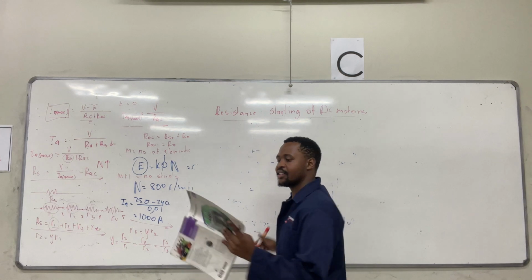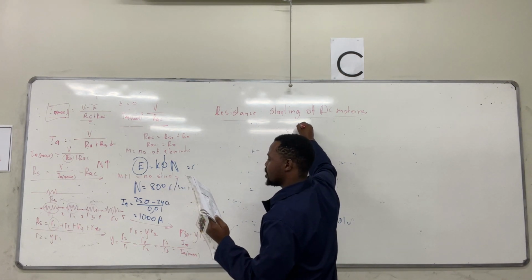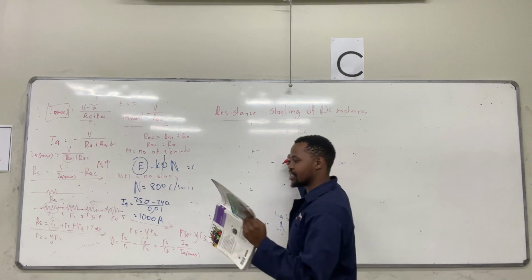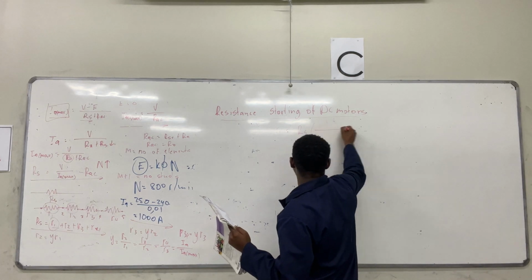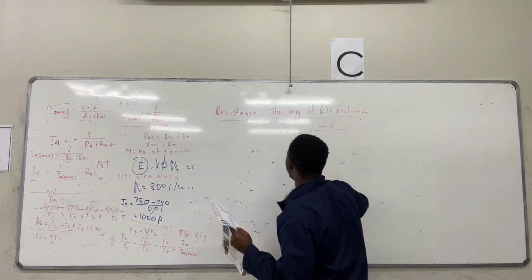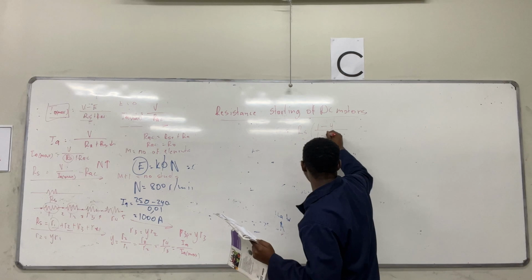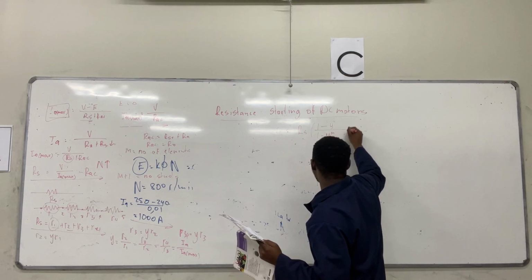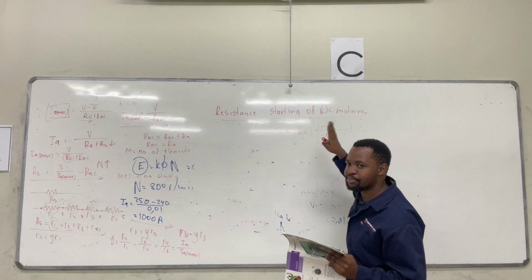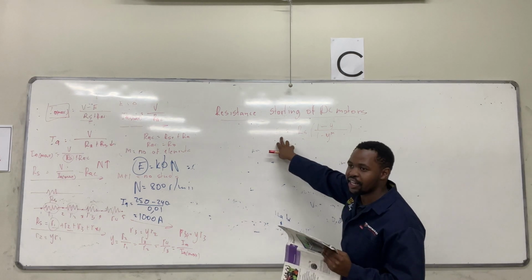For R1, you can find it: R1 equals RS, which is the total starting resistance, times open brackets 1 minus Y, the fixed value, over 1 minus Y to the power M, the number of elements, which is 4. You get R1.